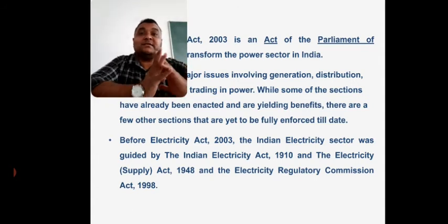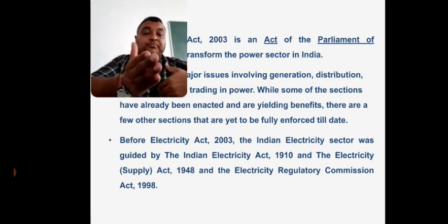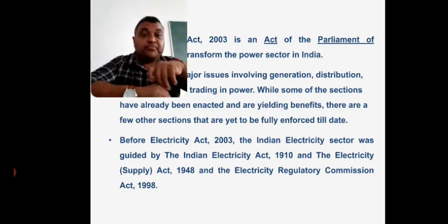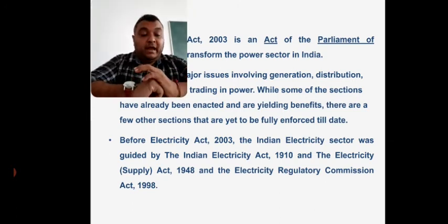Then interconnection of systems led to standardization of frequency, because when we make an interconnection of power systems, it is necessary that the frequency is managed within the limit and should not vary with respect to time. In different countries there are different frequencies of power system. Like in the US it is 60 hertz, in India it is 50 hertz that should be maintained in the power system.